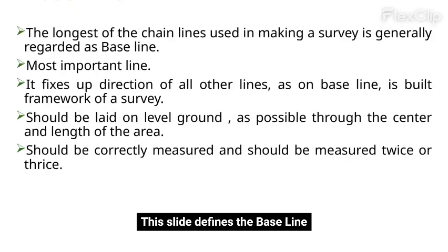This slide defines the baseline as the longest chain line, considered the most important line as it fixes the direction of all other lines and forms the framework of the survey. It should be laid on level ground, ideally through the center and length of the area, and measured correctly multiple times.